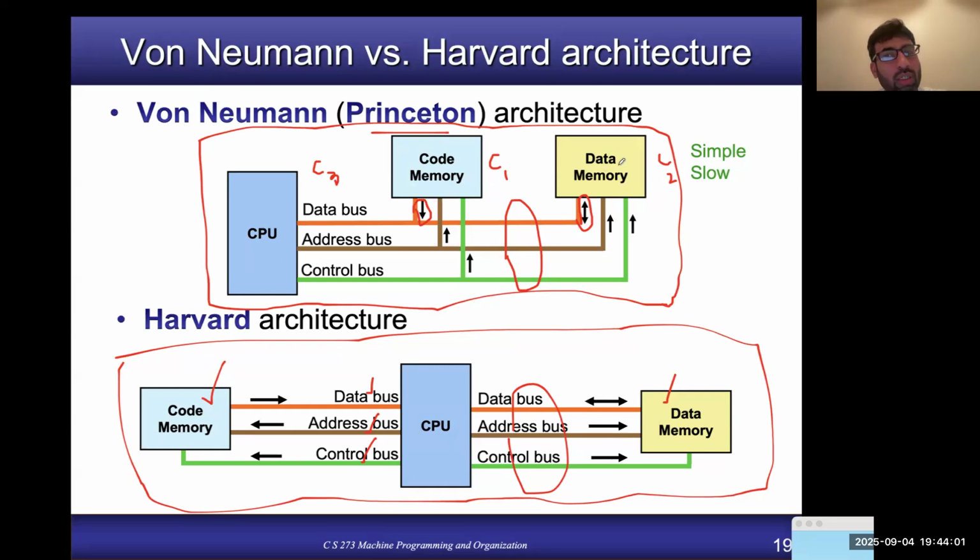You need a much higher capacity for the memory, and that higher capacity cannot be put on the CPU, so you cannot use the Harvard architecture. You have to use the Princeton architecture, because you have to have a separate memory chip due to the larger memory capacity which is typically needed by the applications or workloads running on your desktop or laptop computers.